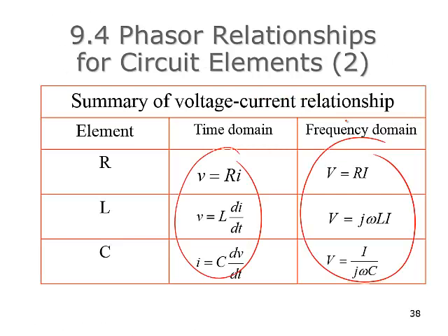Oh, do you want to see those again? So V equals j omega L I for the inductor. That's basically Ohm's law for the inductor. And normally it's written with a minus sign for the capacitor. So V equals minus j over omega C times phasor I.